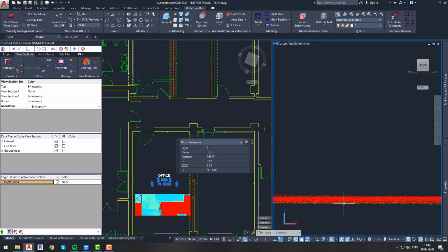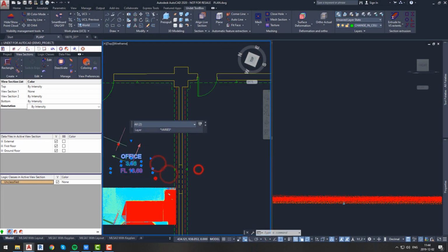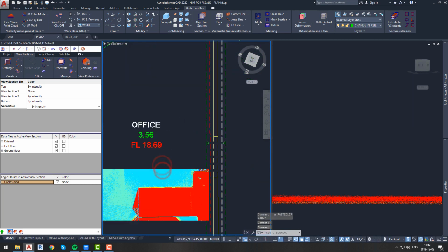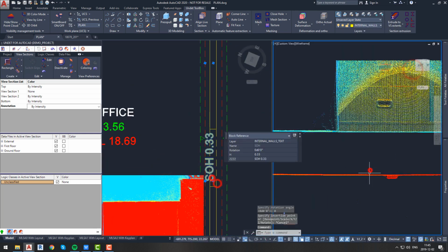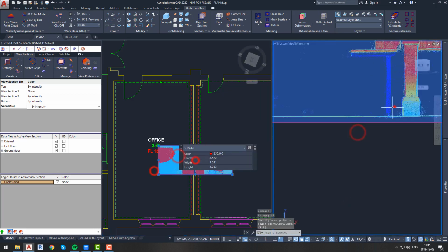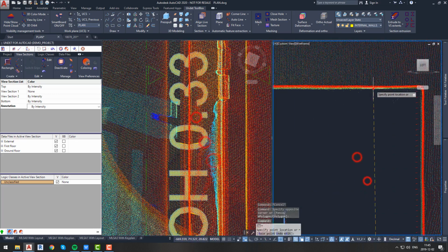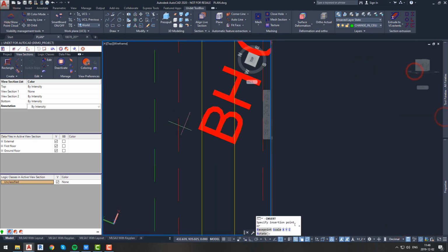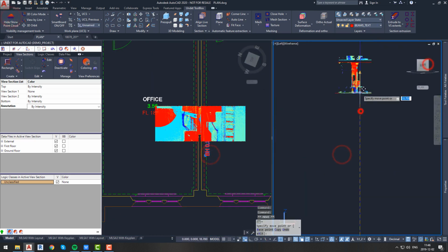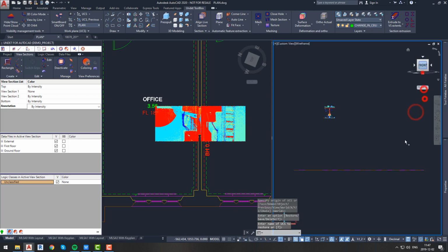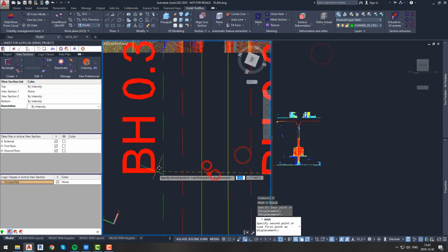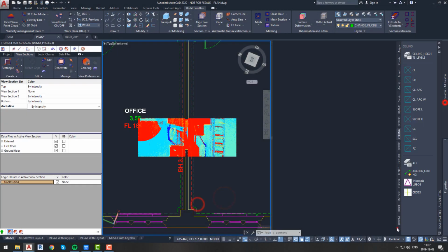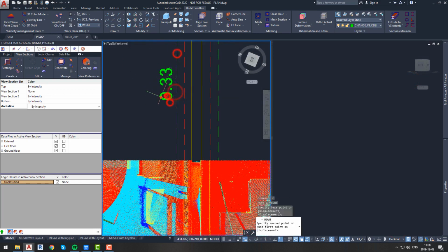Next we can move on to internal soffit and beams annotation. It all depends on what type of annotation we are choosing. If we are showing object height, we will have to lift our annotation to floor level, and then adjust the grip to our selected object height, but if we are showing object level annotation, we can lift our annotation to the selected object level straight away. Once again, those annotation values will be affected only after we save the drawing.